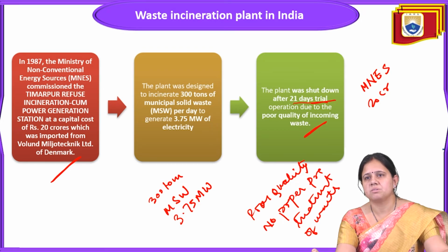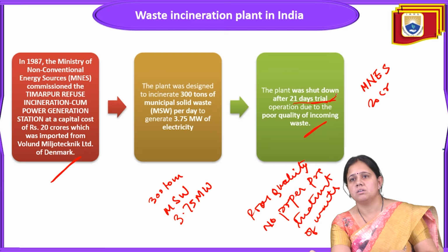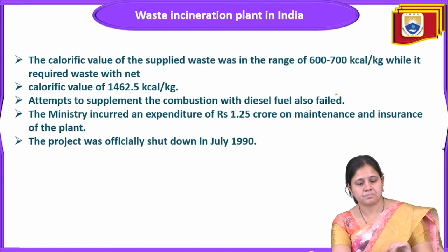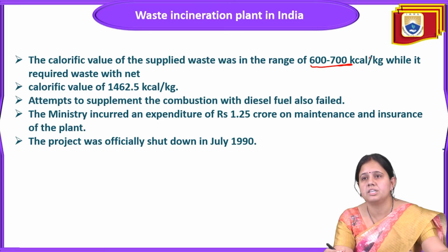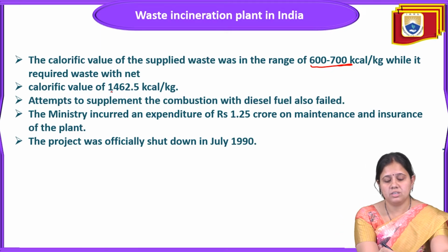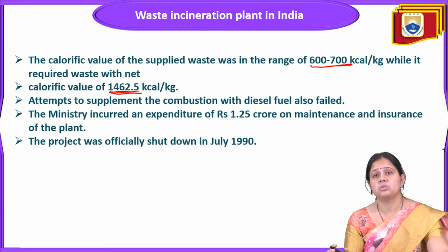But this plant was shut down after 21 days of trial period only, because of the poor quality of waste. So what happened? The calorific value of the supplied waste was in the range of 600 to 700 kilocalorie per kg, while the plant required waste with a net calorific value of 1462.5. So the calorific value should be high.